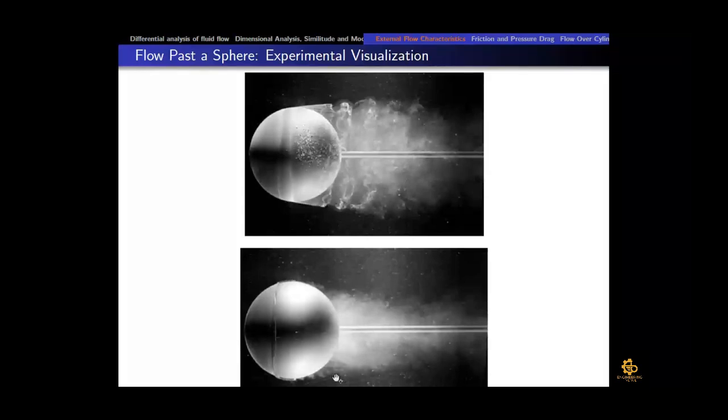So there would be a vertical pressure difference as well. So that's why the ball moves in here. That is basically the entire phenomenon of reverse swing: we make one side shiny so that the boundary layer remains laminar, and it separates at theta equal to 80 degrees, while the other side, which is rough, has a boundary layer that becomes turbulent and remains attached. So that's why the flow separation happens at theta equal to 140 degrees.